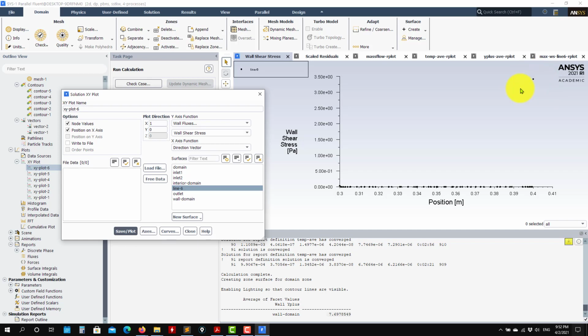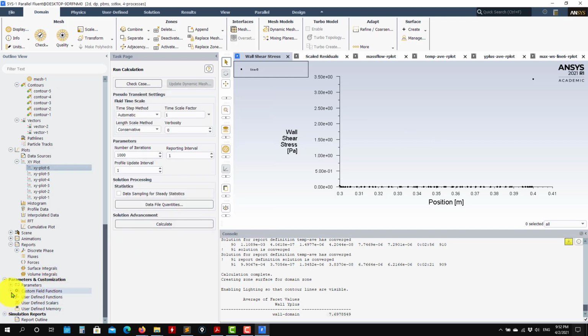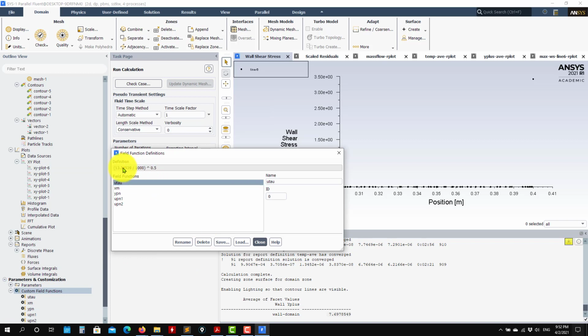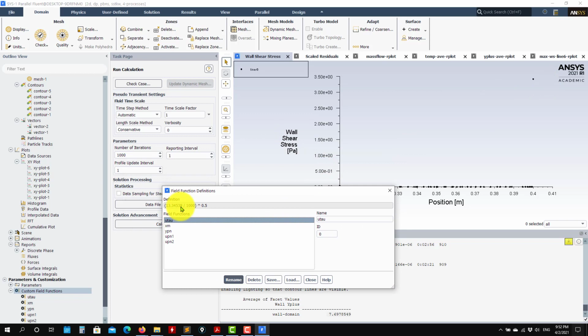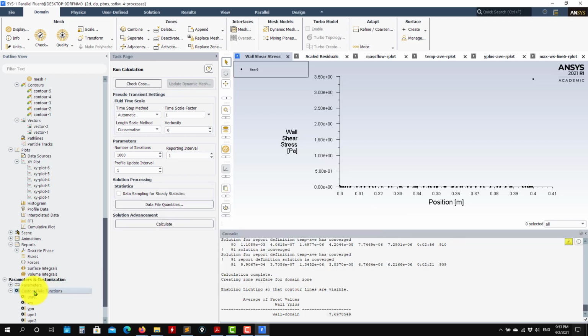Actually, in this case, by the way, as you are running your case, you should also recompute your shear velocity, because in this case the shear velocity U tau is computed using this value, which is very different from the one that we have computed. So this should be corrected. Be careful, you should recompute this quantity, U tau. Let me do it just to show you.